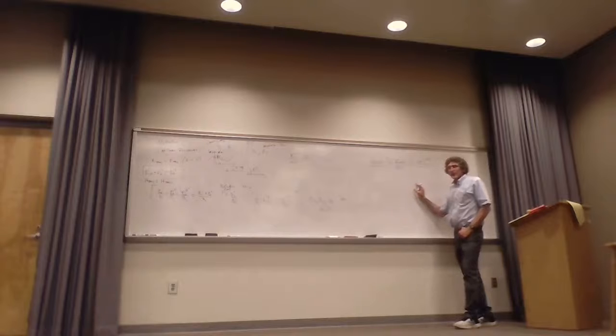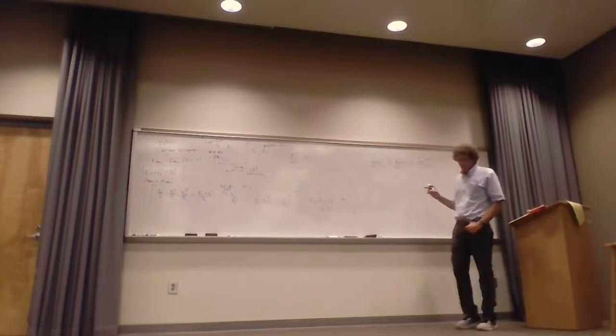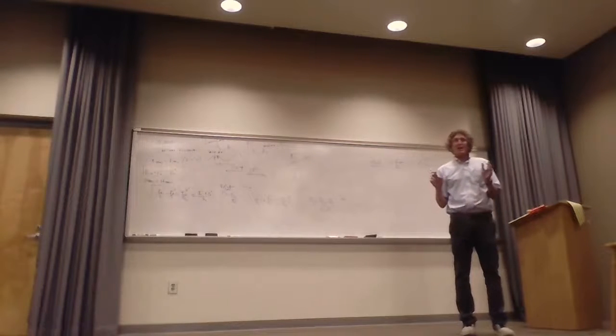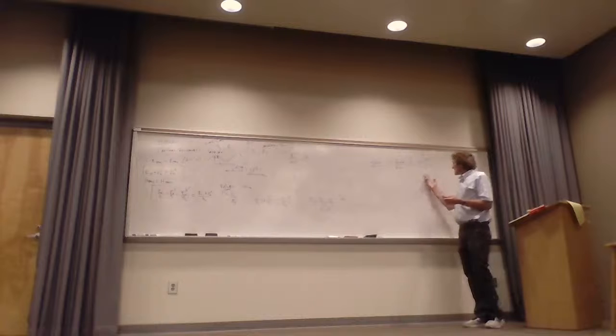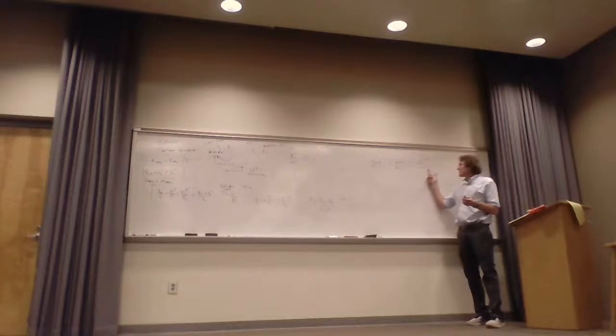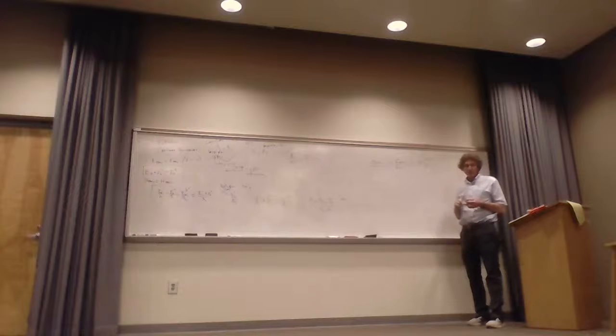I don't know how much you remember about standing wave ratio, but the maximum value it can have is infinity, because if gamma is 1, and it can easily be 1, then 1 minus 1 is 0, and it goes to infinity. And the lowest possible value is 1. That's when the reflection coefficient is 0. When the reflection coefficient is 0, then I get 1 over 1.